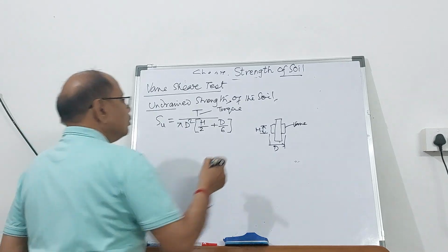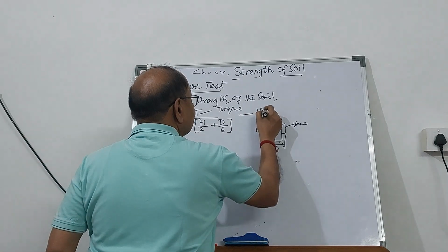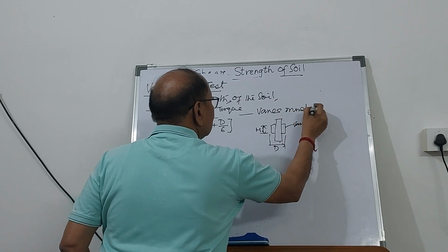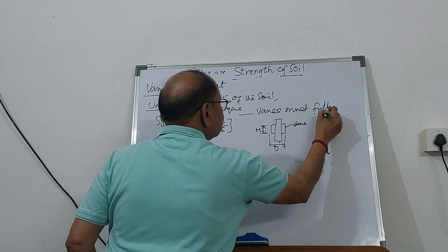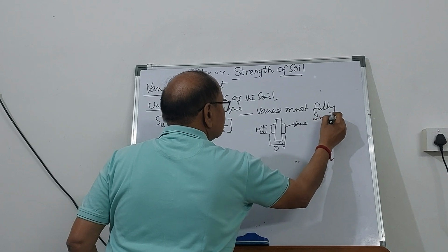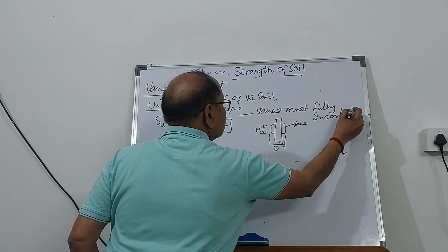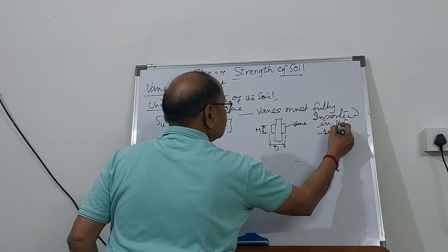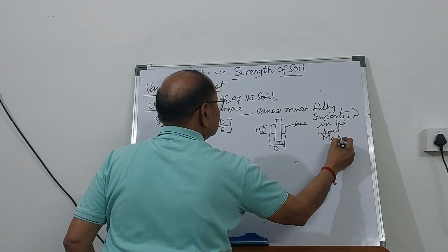The external torque to shear the soil sample can be easily measured. But the vanes should be here. The only condition is the vanes must be fully inserted in the soil mass. That is the condition.